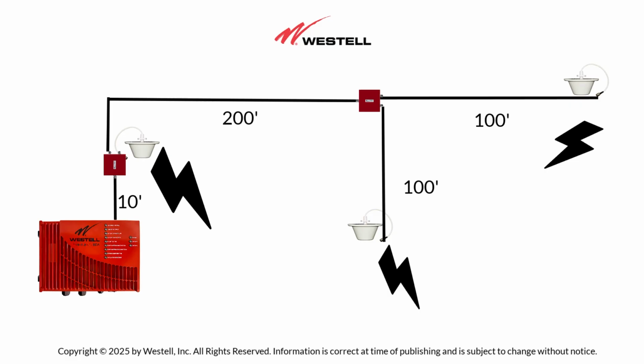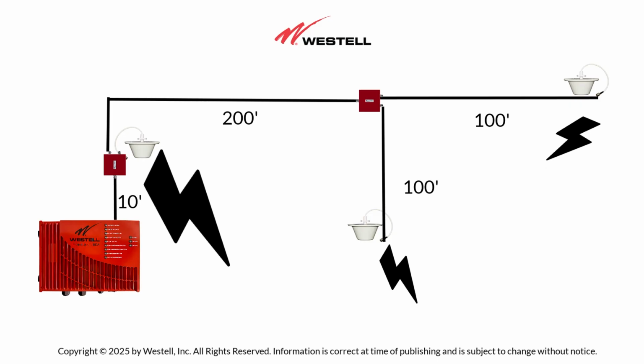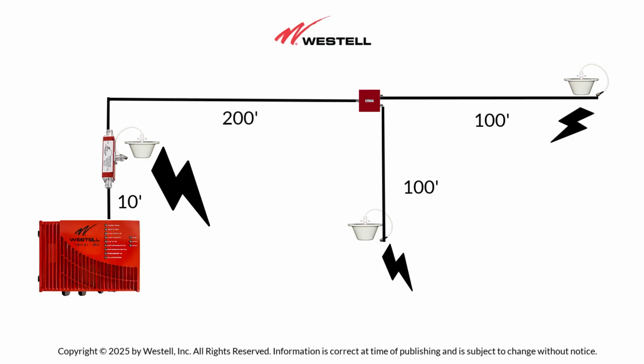A nearby antenna may experience minimal signal loss, while a distant antenna might suffer from long coaxial cable runs and multiple splitters. This is where an unequal power divider comes into play. When the BDA supplies power to a nearby antenna, the unequal power divider intentionally reduces the power sent to it, while directing the majority of the power to the antennas that are farther away. This added attenuation is calculated to compensate for the signal loss that occurs due to the coaxial cable and splitter losses on the far antenna. Design software can accurately calculate the necessary attenuation values to achieve a balanced system.